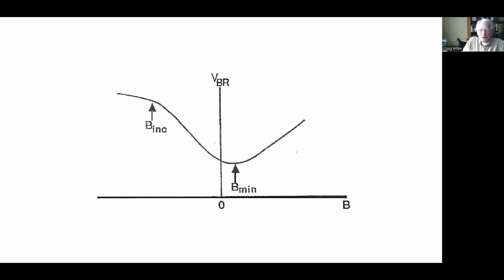Now, normally you don't worry about magnetic fields, but of course, particularly in accelerators, there's going to be significant magnetic field presence. So the effect of magnetic fields on surface flashover has to be considered. This is a typical experimental result, which also agrees with calculations. If the magnetic field is driving the emitted electrons into the insulator, you decrease the flashover voltage somewhat. Then as you're driving them in faster, it increases. Very similar to the effect of cone angle.